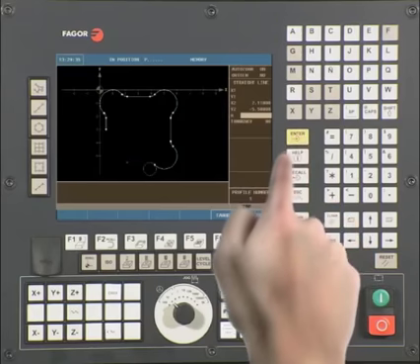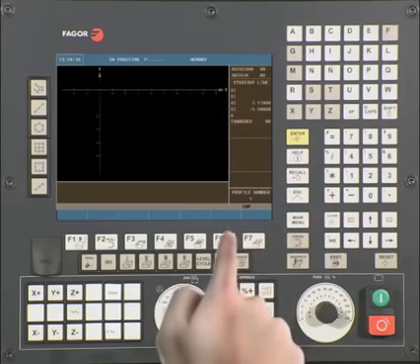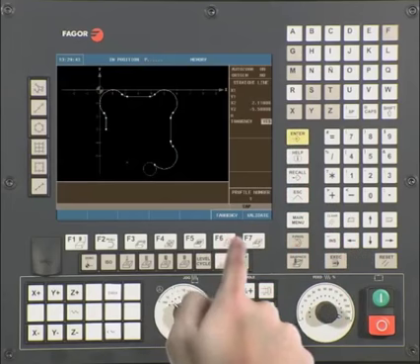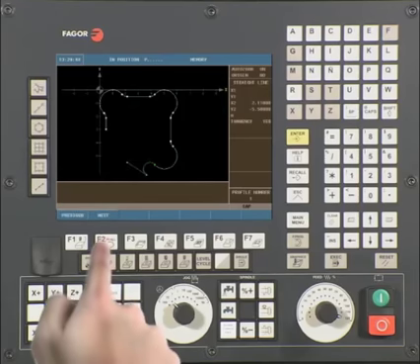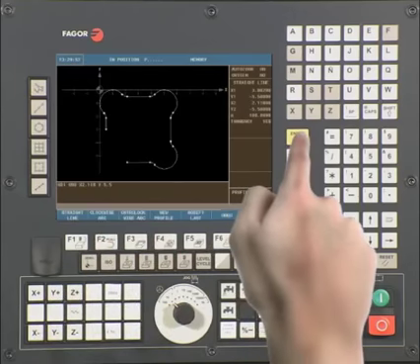Set tangency to yes. Validate the data. There are multiple intersecting points with this line or arc. The CNC will prompt you to select the correct intersecting point. Press Next to see the different intersecting points. Press Enter to confirm the correct one. Select counterclockwise arc.